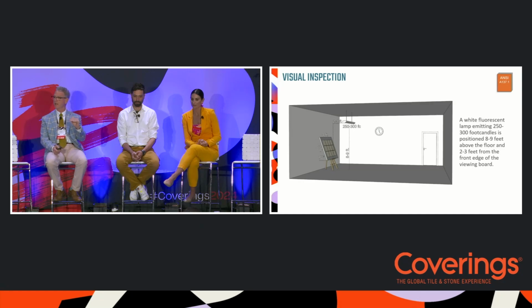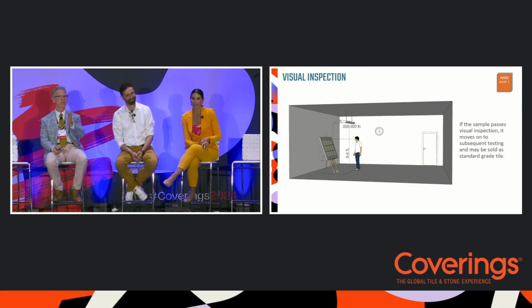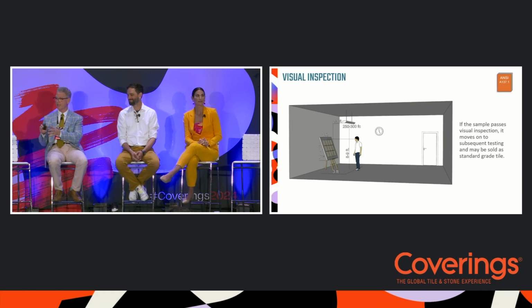There's a certain light fixture, a certain dimension from the easel, and an individual with perfect vision who's not colorblind stands 3 feet away, and there's usually a timekeeper in the room, and looks at those tiles and examines them for visual defects. And that individual has 6 seconds per square foot to view that tile. And if there are no defects, it passes and it can go on to have further structural testing, and it can be sold as a first grade or a standard grade tile, which is the best of all tiles.